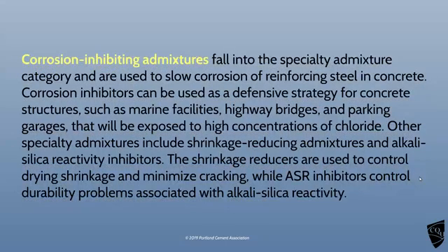You can chuck in corrosion-inhibiting admixtures, very important if you've got reinforced concrete. They're a specialist one. You can put those in, and that inhibits the metal reinforcement from corroding within the concrete itself.